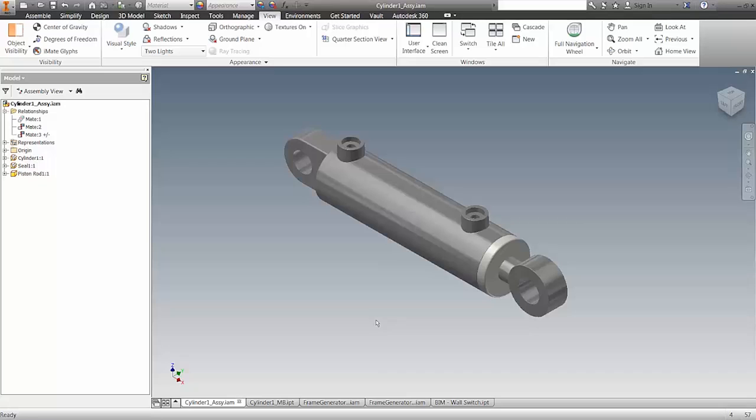This workflow can seriously decrease rework time by creating a domino effect in part updates. The traditional bottom-up method would mean each of the components in this assembly, in this case the cylinder, the seal and the piston rod, would have to be updated individually and then double checked to make sure the changes aren't clashing with other parts in the assembly. You can imagine this would take quite a lot of time. Where possible, I strongly recommend adopting the multi-body top-down modeling method to reduce time spent adjusting components in an assembly.